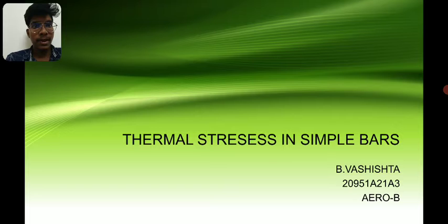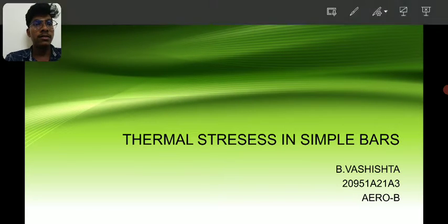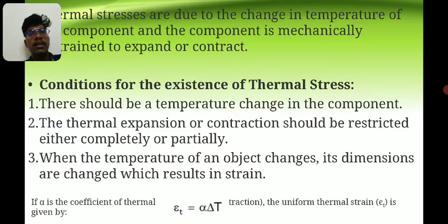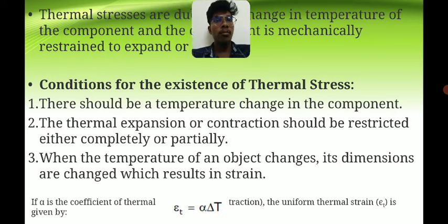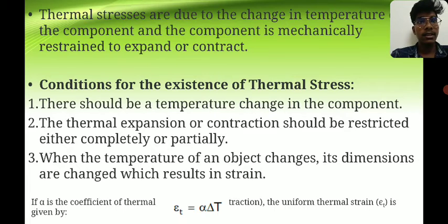Today I am going to explain about thermal stresses in simple bars. So, coming to the topic, thermal stresses are due to the change in temperature of the component, and the component is mechanically restrained to expand or contract. Conditions for the existence of a thermal stress: there should be temperature change in the component. The thermal expansion and contraction should be restricted either completely or partially.